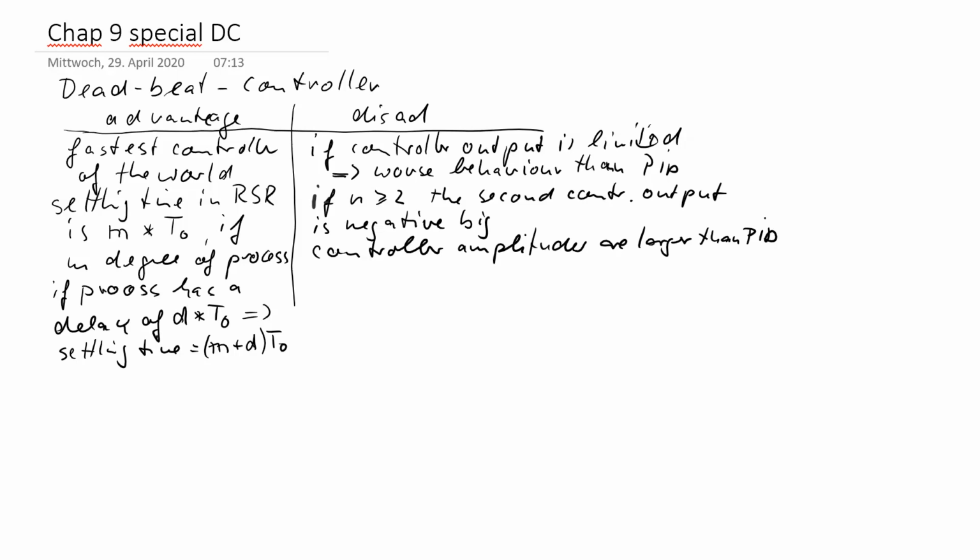That's an advantage. You will see in our real algorithm, note there we have a d which is 1. Yeah, then there is a delay. Our real algorithm, the programming kind of a real algorithm, produced one delay, but this can be realized with a deadbeat control algorithm.